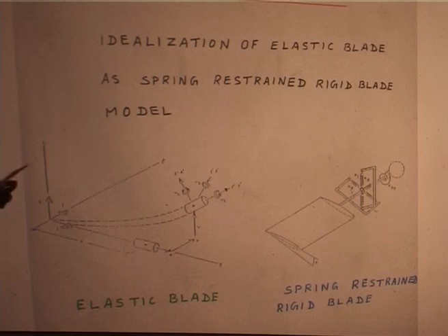Now, this is the model of an elastic blade. If you want to follow systematically, it is basically a displacement formulation. You assume a displacement and then get the strain, then go to stress and then write your equilibrium equation. From there the standard technique starts, but of course you have to take the centrifugal load into account.